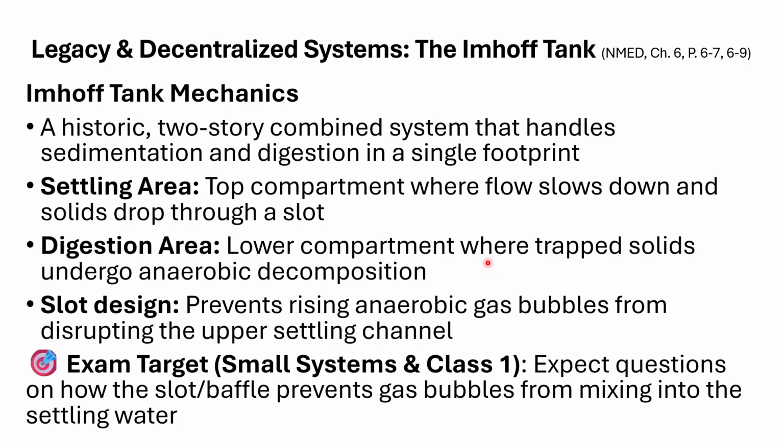That's where those trapped solids are going to undergo not aerobic, which is the oxygen rich environment. They're going to get decomposed via anaerobic decomposition, which means there's no dissolved oxygen present for this process. So that's the difference between a combined unit and an Imhoff tank. The big difference: the combined unit is going to have an aerobic process for decomposition in the digester.